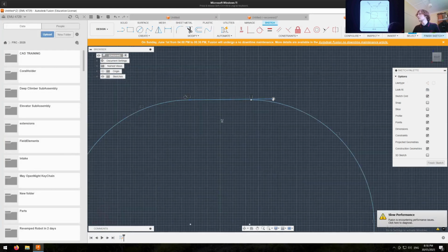I have no clue what's happening here, but luckily with the Power of Fusion, I can just kind of click and drag it. And then, oh wait, no, it's not letting me snap. Okay, so how do I get these two lines to connect? Because obviously in the drawing, it's one full line. How do I make that happen? It's this lovely menu that I haven't talked about yet, but I was alluding to. Constraints. These are really cool.